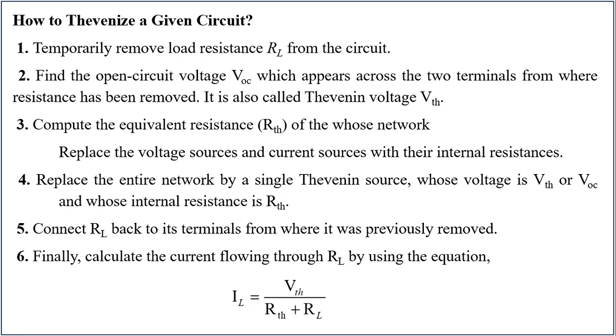The next step is to compute the equivalent resistance. Calculate the equivalent resistance by replacing the voltage sources and current sources with their internal resistances.